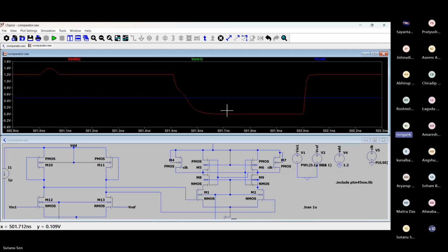That means even up to maybe 2, 3 gigahertz of clock frequency, it will work. But beyond that, because the settling time becomes comparable to the clock phase, it will start giving errors. It will not work properly. And remember that we had discussed the concept of corner simulation. The speed will be determined by the worst case corner, say the slow corner, and then we can decide at what speed the circuit is able to operate.